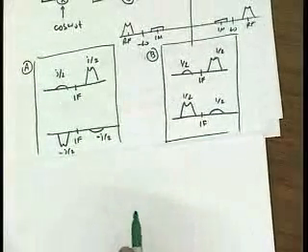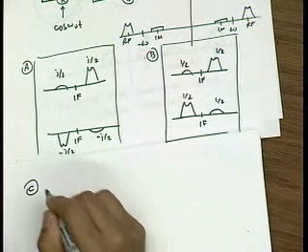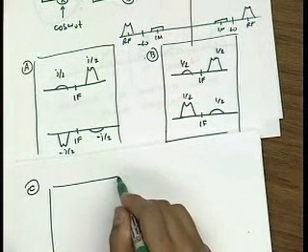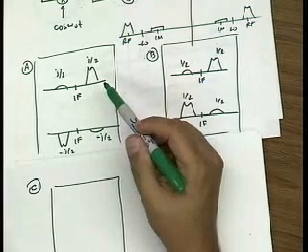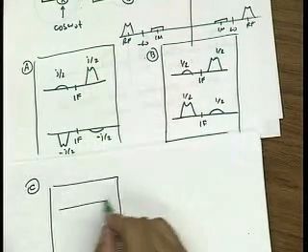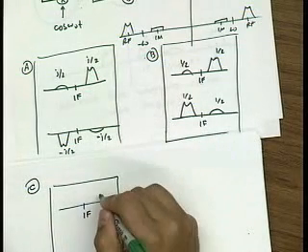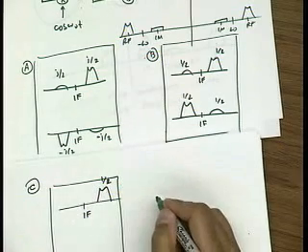So this is going to be at point C, which is a shifted version of A. Okay? So when I shift this, I multiply by minus j at the positive frequencies. So this just turns into 1/2.